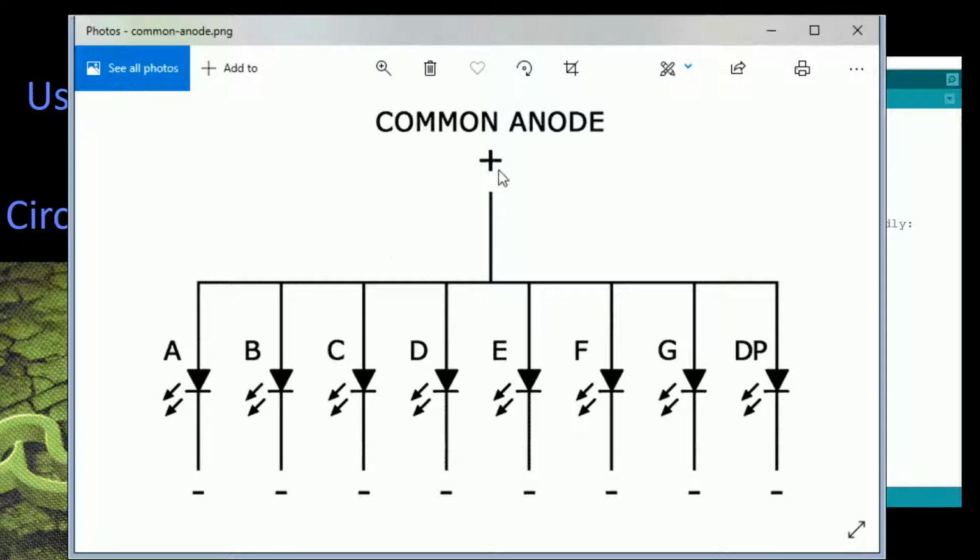So when we're actually doing this, A, B, C, F, and G are the 5 pins we needed to connect to ground. What we would do in the program is connect all of these to positive, and we connect this to positive. By doing that, there's no current flow because we have 5 volts on both sides of the diode. We add a resistor to the common anode lead, and I'll show you that when I show you how the wiring is connected on the Arduino board. And by putting a resistor in here, we limit the current to what one LED draws.